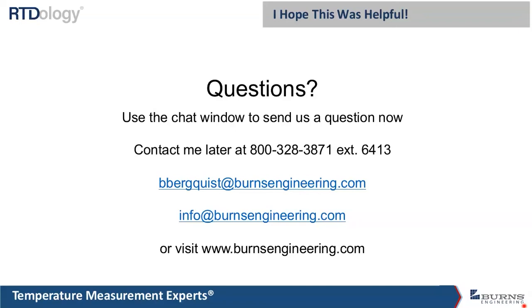Yeah, I think typically the NEMA requirements are on the head itself. So if that was assembled in the field and everything was assembled correctly, it would meet any water, dust, ingress requirements that it has. The FM, or the explosion proof, is different than NEMA, and that's where it's really dependent upon what has been tested and classified and exactly what the approval is as to how that needs to be assembled, whether it needs to be assembled ahead of time or can be assembled in the field.